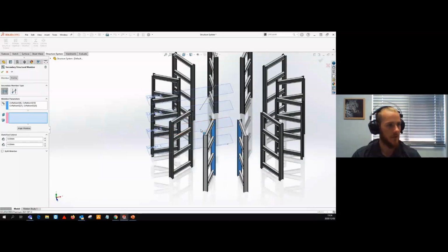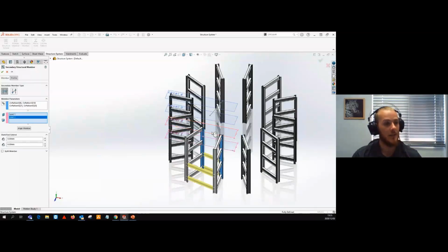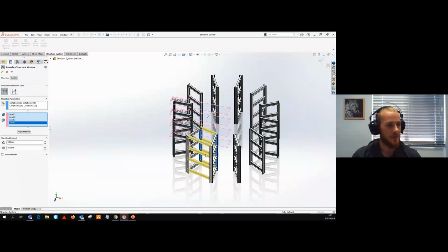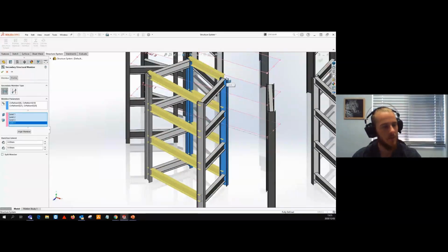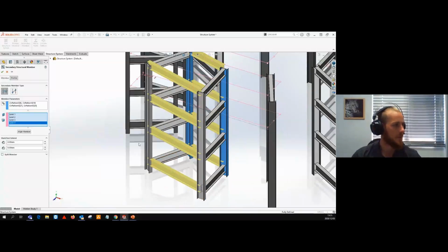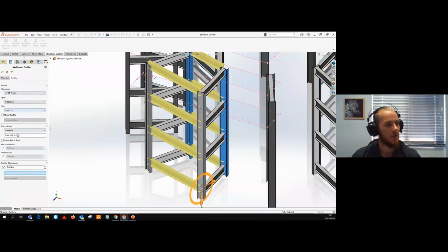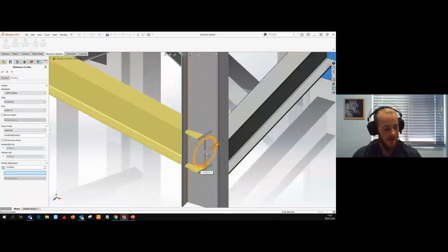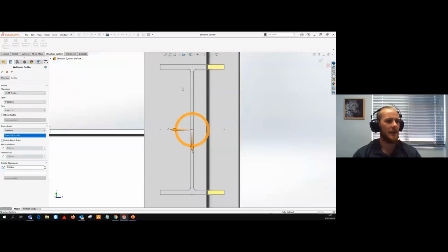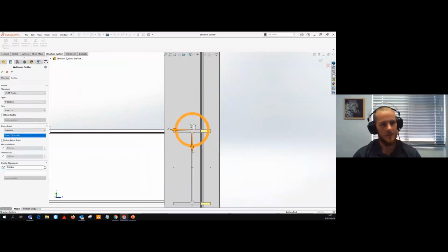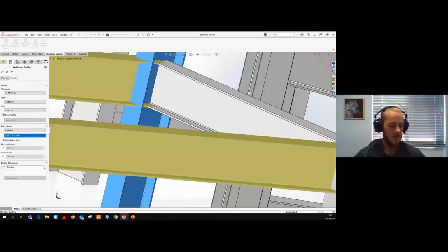So just to quickly show you guys how this is done, I'm simply clicking on the planes. I hope this display is not playing with your eyes too much, but I just want to make it known to you guys, I am only clicking on the planes to host the new reference for positioning. So from here, it's as easy as either changing or updating the profile. Here, I'd like to edit the way the actual segment meets the point, and I'm going to click on the pierce point just to line up this beam with the planes as well. So I just assign a new pierce point and say, okay.